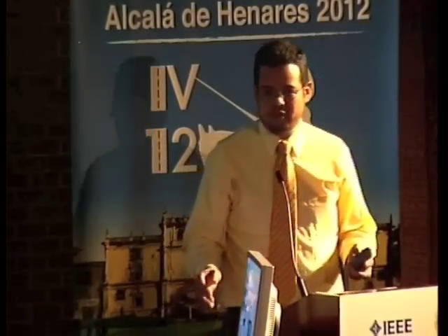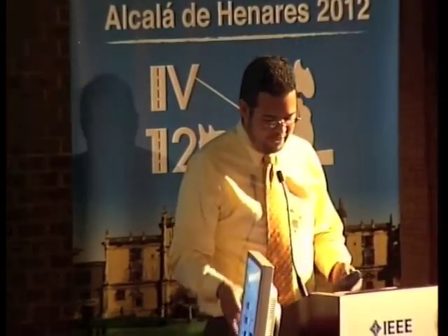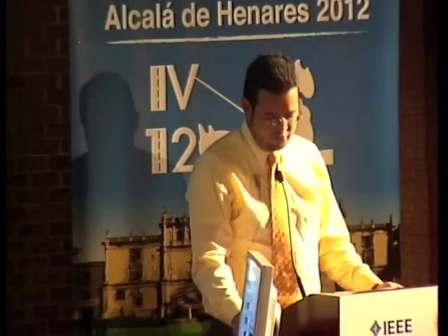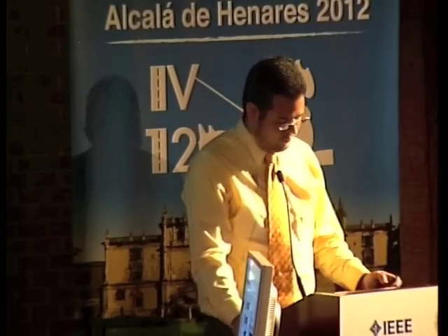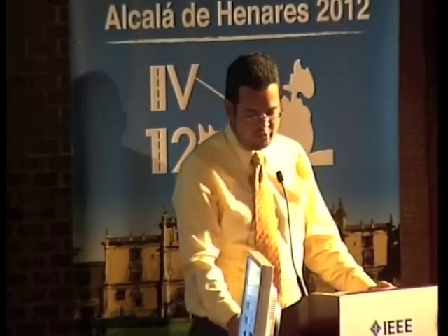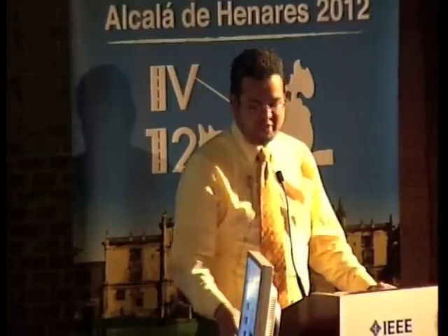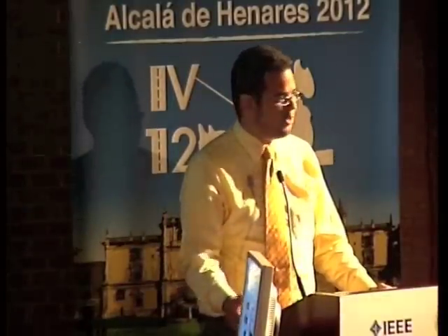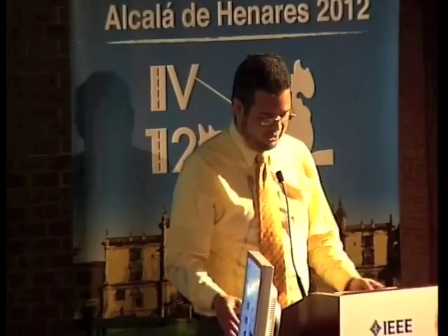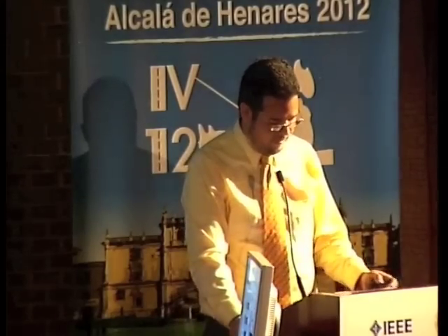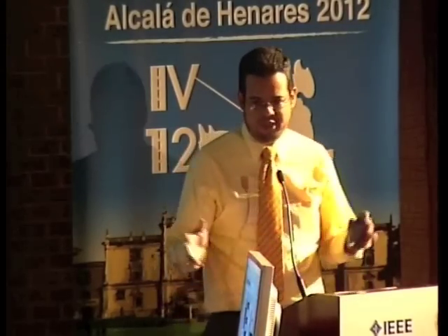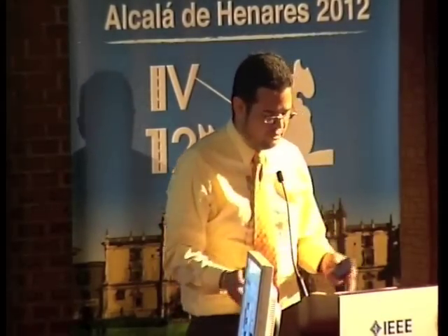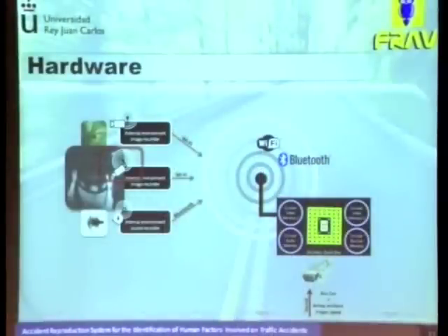These three systems were implemented inside a vehicle computer made by the GMB company. The computer is controlled by an ARM processor running under Linux. It comes with several USB interfaces that allow the connection of a wireless adapter and a Bluetooth radio for communication with the acquisition devices. For the acquisition of the internal environment of the driver, an IP camera was employed in order to acquire images from the driver's top view.